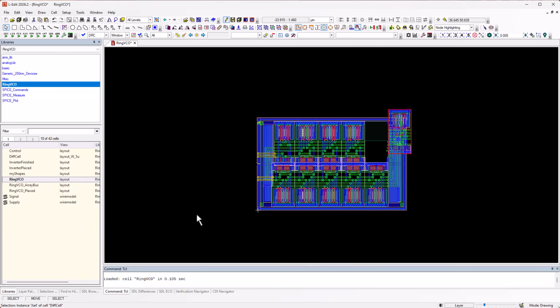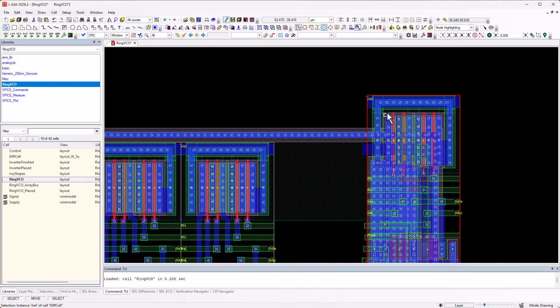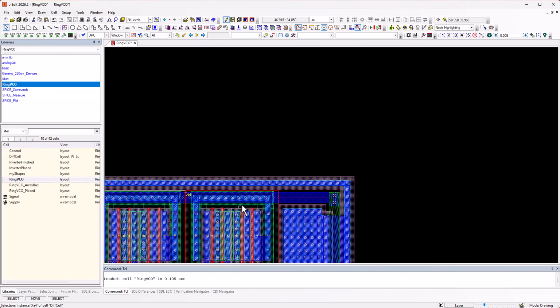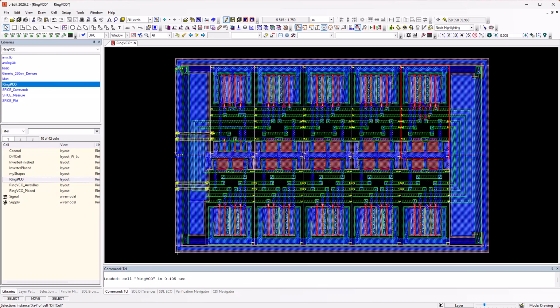Simply choose the edge that matters and align directly to the target. Here I'm going to align using my VDD rail. I'm going to set my Basepoint here, select my object to move, and I'm just going to use my middle mouse button to align these to each other. So no helper geometry, no calculations, just accurate placement.